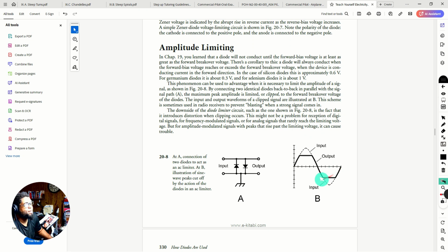If you're looking at this, you can probably see what might happen and why we might want to use something like this. In the dashed line, what we see is a sine wave, but as it's clipped, that's how we get something like a square wave. If we do a little bit more, you can do some filtering. You could change the timing of the circuit. You would get a little bit more of a square shape. So this is a way that we could have a square waveform using a clipped signal.